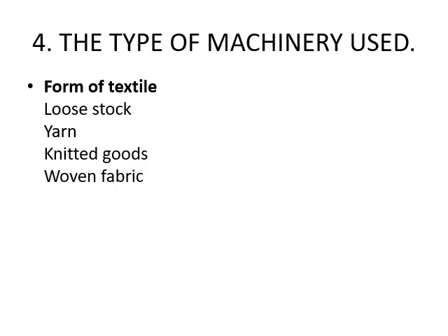For fiber processing, batch size is important, because the machine for fiber processing is selected depending on batch size. For yarn processing, hank or package form decides the machine. In the case of knitted goods, whether the knit is in tubular or slit form is considered before selecting the machine. For woven fabric, processing is done either in rope form or open width form, and the quality of the fabric decides the machine.